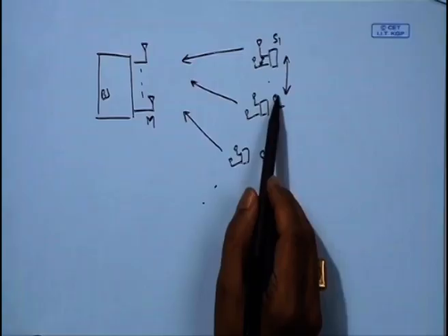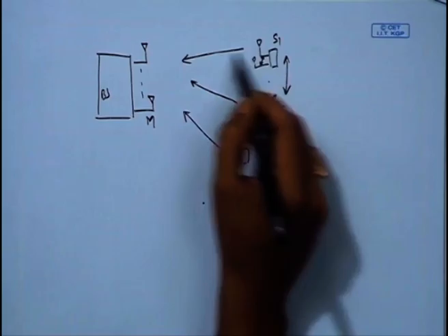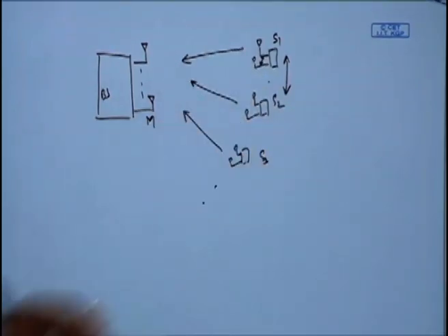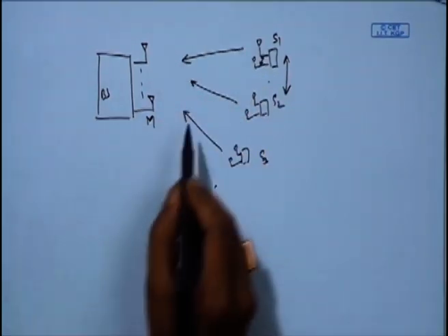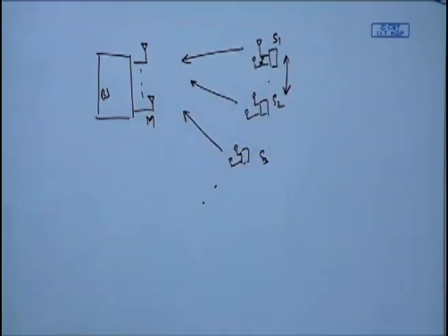And we have also studied the effect of correlation, that when there is more correlation between the antennas, two things happen: the diversity gain decreases and the capacity gain decreases. Whereas when we have this particular situation, since antenna separation is large, it is of low probability that there will be high correlation. So all these links can be of almost independent nature. In this case, you can almost achieve m parallel links that are getting transmitted.